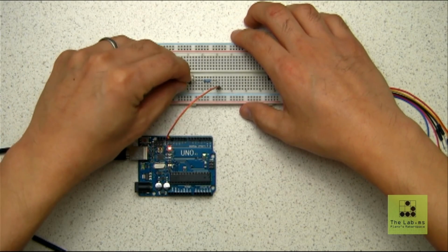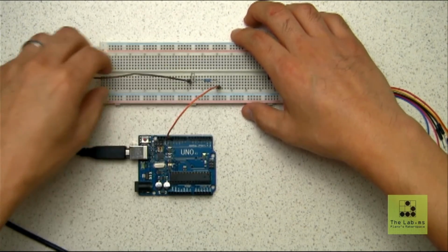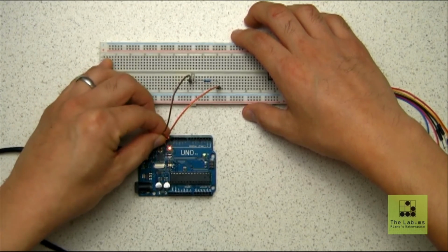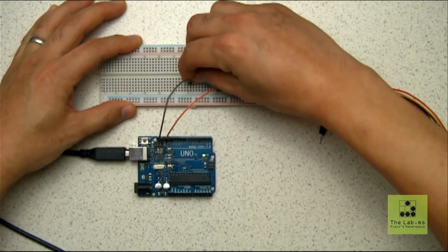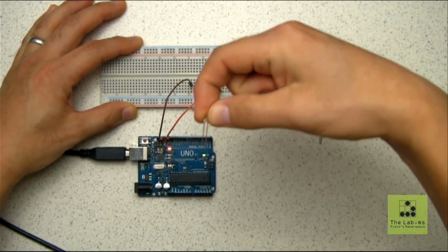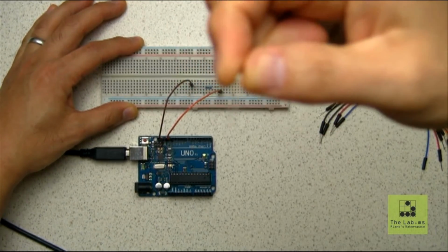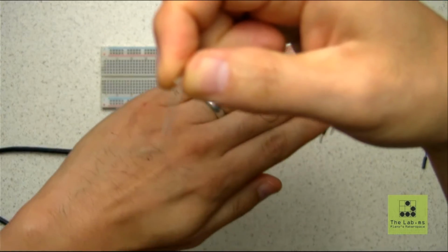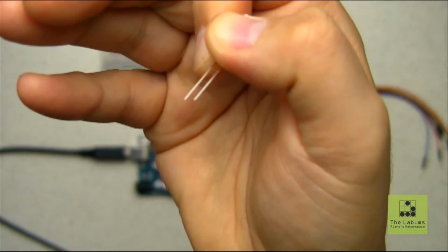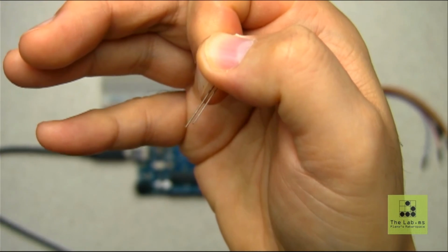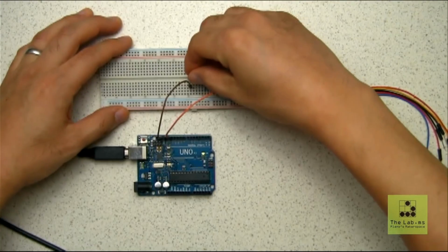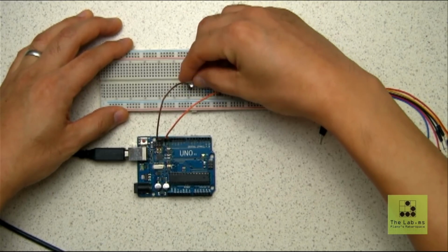All right, so then we're going to connect the other end of this to ground, and if I have my LED oriented correctly, this will light up, and I do not. So the interesting thing about LEDs is that, since they're diodes, they are directional. So the electricity only flows one way. I'm not going to get this to focus, but you can see one leg is longer than the other, so that should tell you which way it goes, and I'm probably going to put this in wrong again. Nope, there we go, got it.